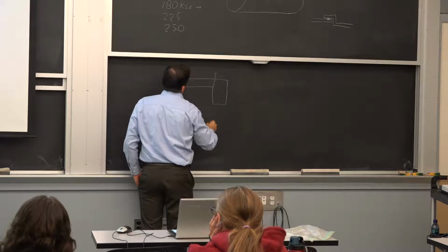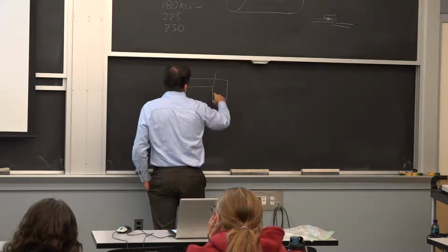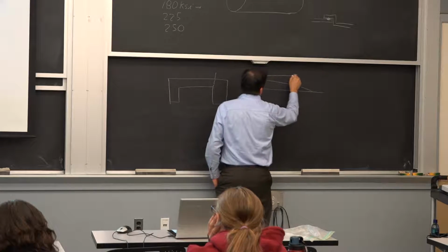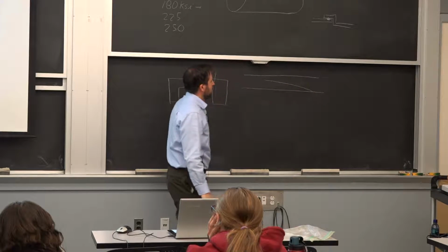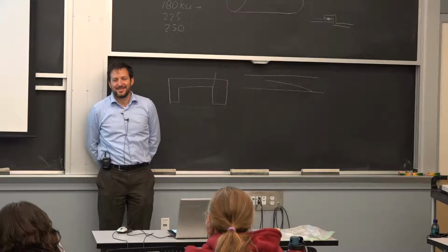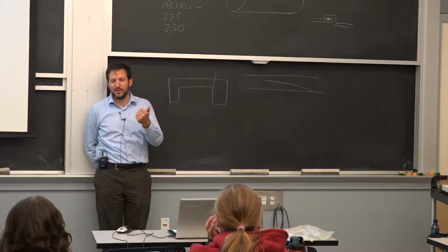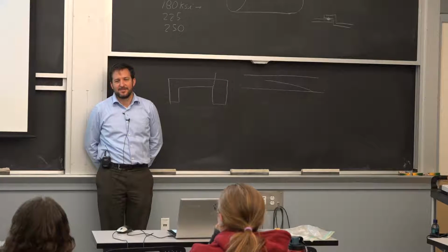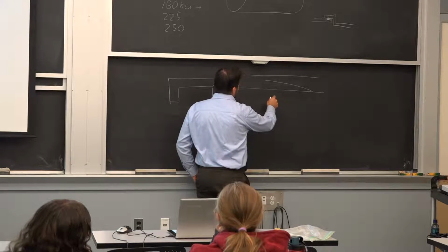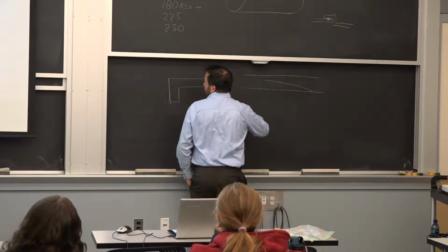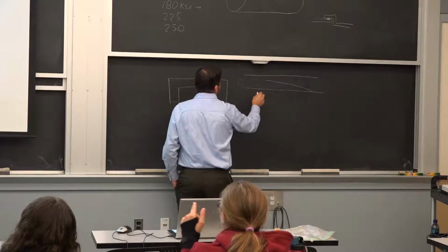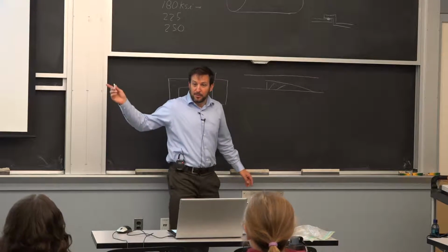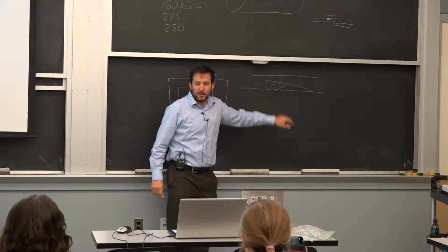That was the crack. So now we're looking at this fracture here, and what you see on one side, if this is the pipe wall, is this line. What kind of line do you think it is? We've only seen two: the crack propagation and the crack arrest line. True, we have both. So let's fix this here. I'm going to help out a little bit. There you go. Now we see both, right? That's propagation and that's the arrest.